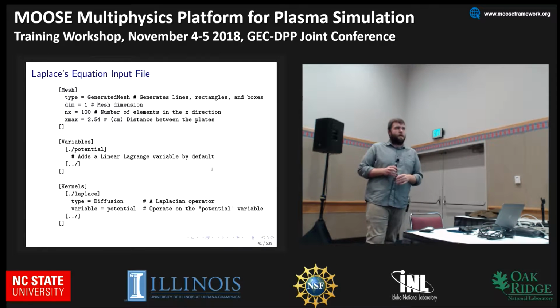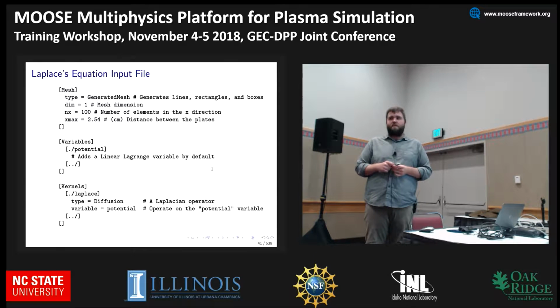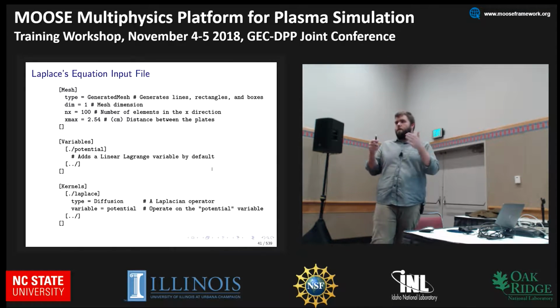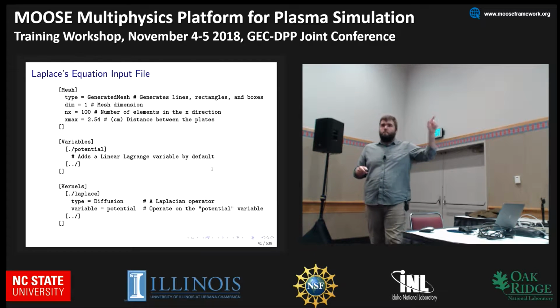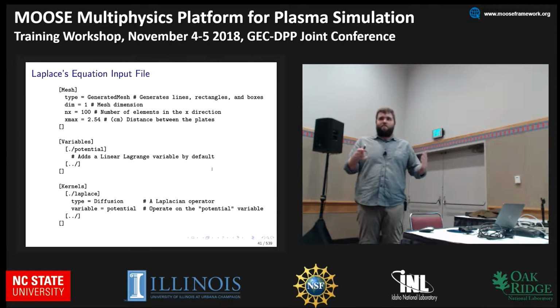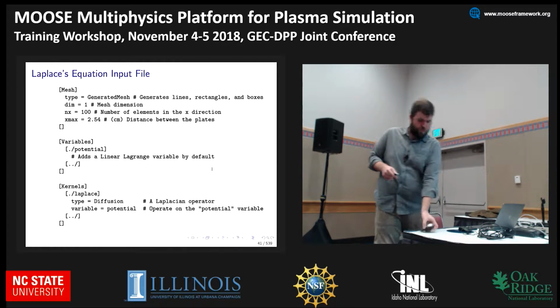If you're working in a system where you have to do a lot of unit conversion, sometimes it may be easier to, and this is done in Zapdos, have your base unit system, but then input things with their native units and scale them as you need to in order to be consistent. You can do that on a code level. You can do that on an input file level, like setting up a global parameter for your units. It's really kind of ad hoc, however you want or need to do it for your problem.